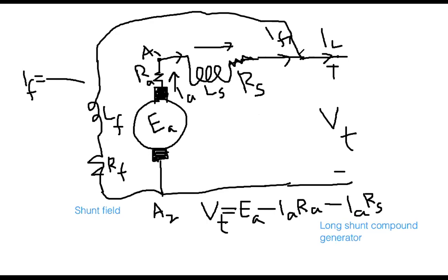You see, this means this is your field circuit. You are measuring voltage between this point and this point. So what is that voltage? Again, the same thing. This is your VT. Ultimately, that is your VT. So if you can get that VT, then VT over RF will be your IF equation.